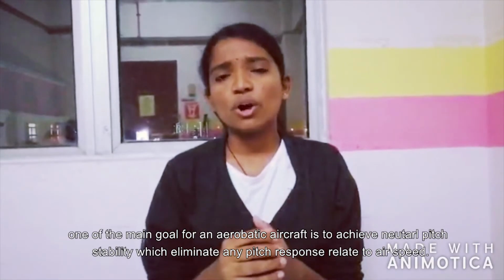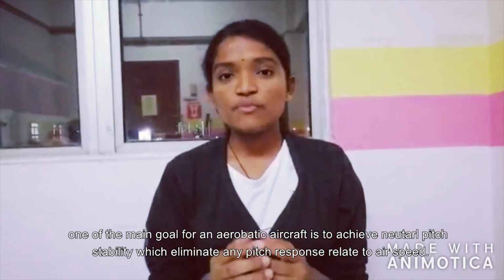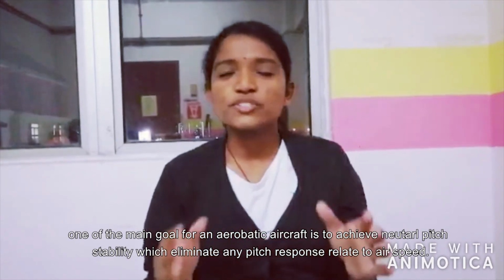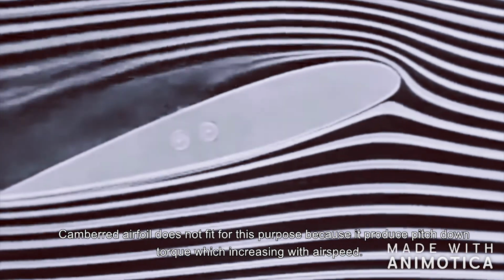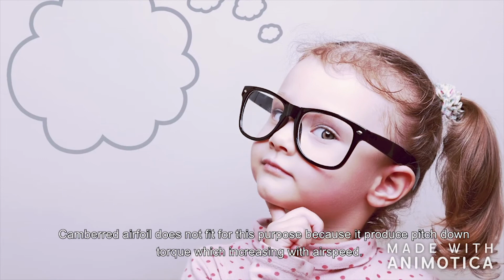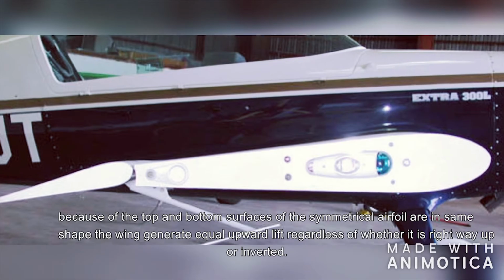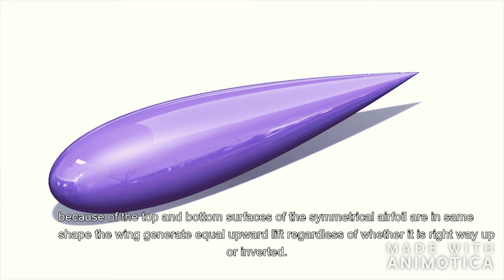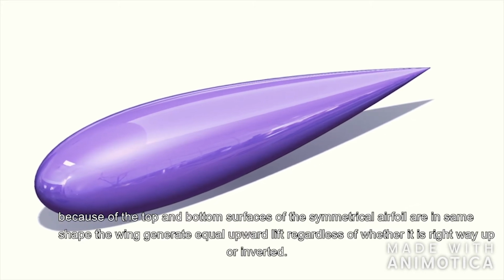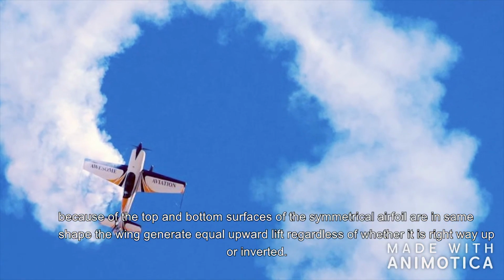One of the main goals of an aerobatic aircraft is to achieve neutral speed stability, which is to eliminate the pitch responses related to airspeed. Cambered airfoil does not fit this purpose because it produces a pitch down torque, which increases with airspeed. So which one is more suitable? Of course, symmetrical airfoil. So most aerobatic aircraft are made with symmetrical airfoil. Because the top and bottom surfaces of a symmetrical airfoil have the same shape, the wing can generate equal upward lift, regardless of whether it is the right way up or inverted.